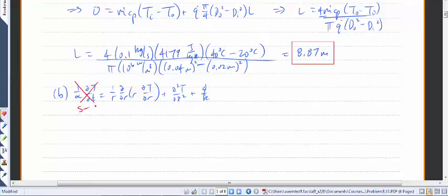We're going to assume that we're at steady state, so that gets rid of that term. We're also going to assume that temperature is only a function of radius r, even though we know that in reality it's a function of z as well, or length or position in the pipe. But we're going to assume that it's only a mild function of z. It's mainly a function of r. So we'll get rid of that term as well. So what we can do then is we can turn these partial derivatives for dT dr into full derivatives. So we get 1 over r, d over dr, r dT dr, plus q dot over k. All this equals 0.